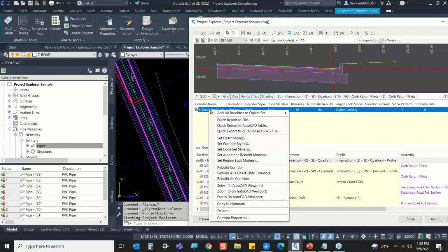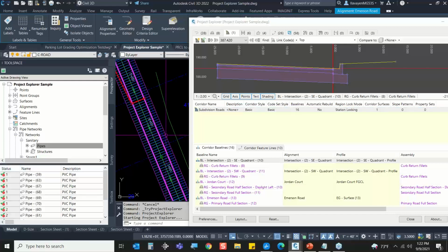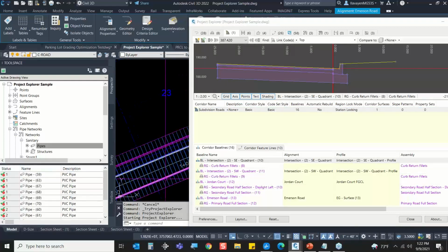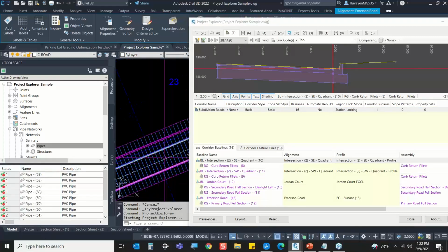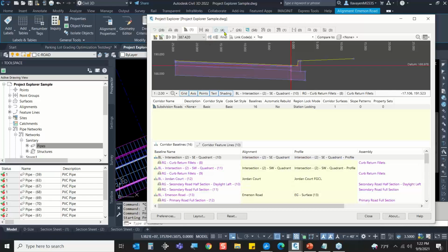And I can go see how my corridor is out of date and choose to rebuild it. And hopefully here I can see how that roadway did step out an extra 12 feet on the pavement piece. And it should show, if I modify the correct piece, there it is, it modified it over here. So you can see how that design does change. And I like how it's modeless, so I'm able to do changes in this box really, really quickly.